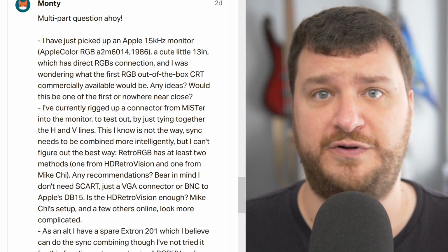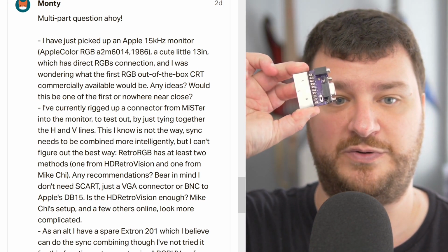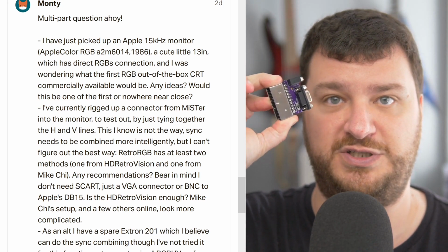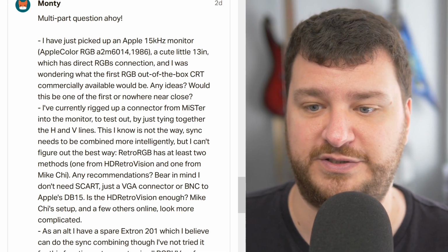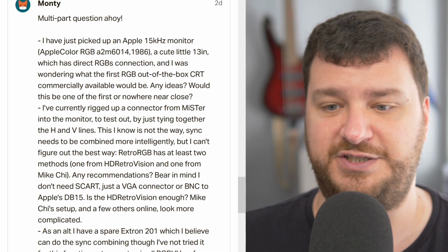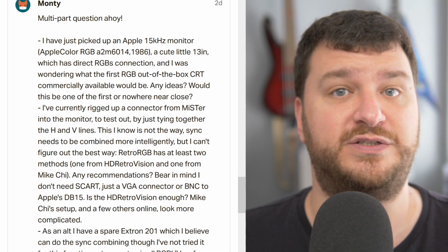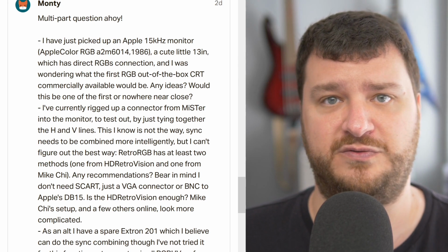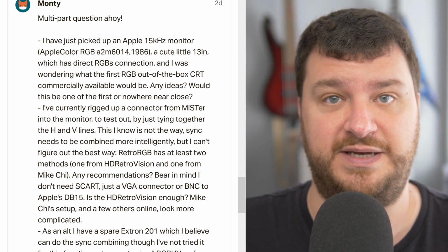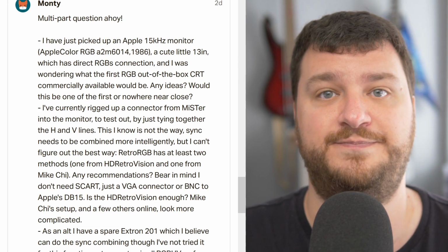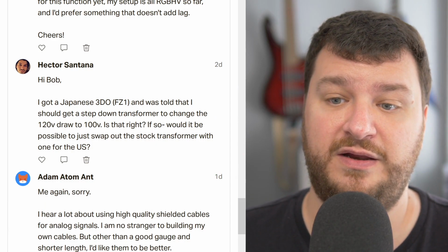I definitely have another video coming out about this soon. I'm probably going to release it about the same time that these things are up for order, because this is the solution to that 100%. So I'll figure all this stuff out and get it released soon. But just as a generalization, if you're going RGBS output into SCART equipment, you're definitely going to need to make sure the voltage is dropped. And if you're going into a monitor, check the monitor and see if it could accept the higher voltage sync or not.